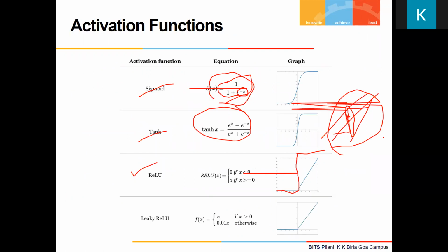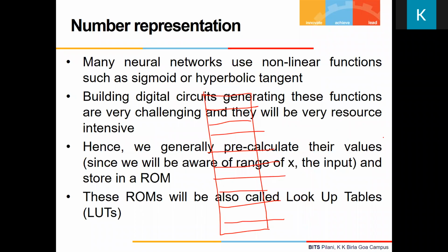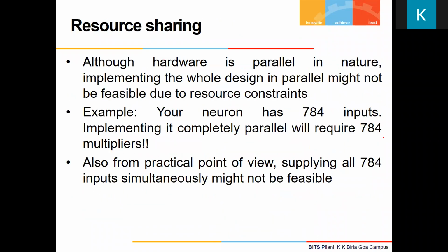Non-linear functions, we will not implement directly in hardware. Instead, we will pre-calculate and implement them using a lookup table. Linear functions, we will do directly in hardware itself, but we need to add saturation logic to make sure the output is within the maximum number that we can represent using the bit width that we have chosen. Okay, now resource sharing.